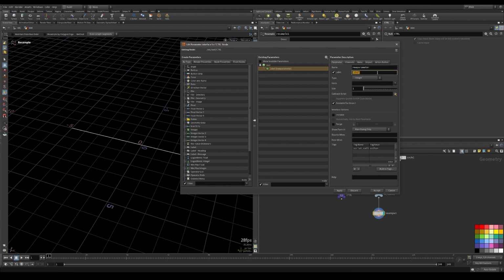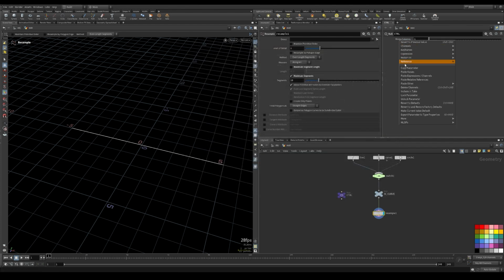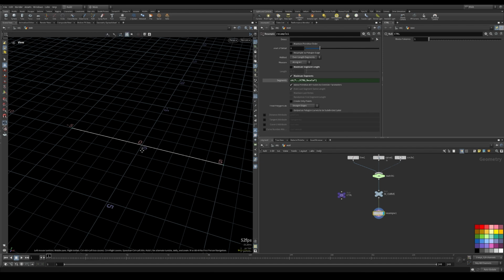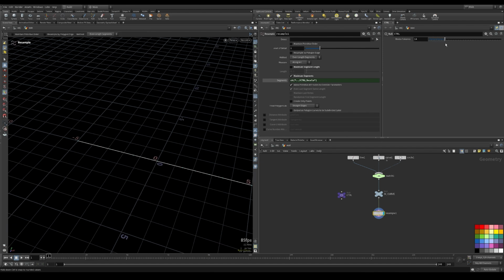This will be called bricks columns, and here on the name, let's call it b cols. For the range, we want at least, let's say, 1 brick, and for this one, let's put something like 60, but do not lock the range. Now we want to copy this parameter and paste the relative reference here. So let's enable the point display, and we already have our first control enabled.